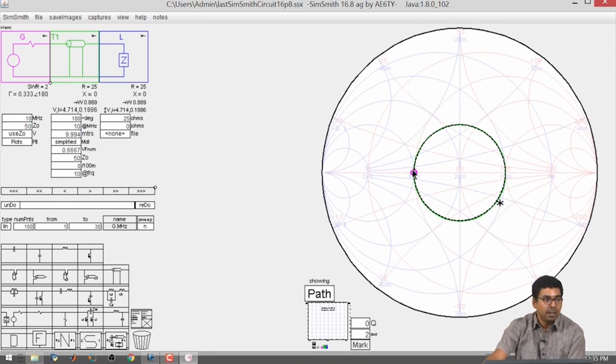We had short circuit and open circuit terminations for the transmission line, and we saw that at every lambda over 2 there will be a zero crossing in your impedance along the length of the transmission line. So, every lambda over 2 the transmission line parameters will again start to match in a lossless case. The actual length of the transmission line really does not matter, only the electrical length matters. Electrical length is beta L, beta is your phase constant multiplied by L. So, it has to sweep 2 pi.